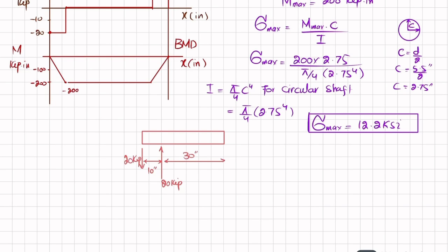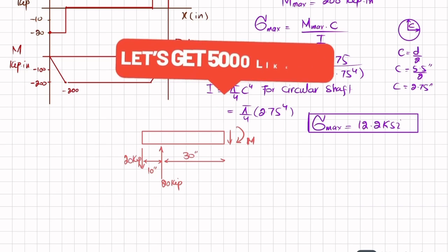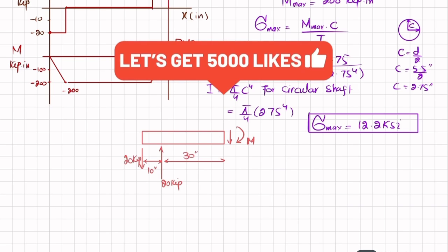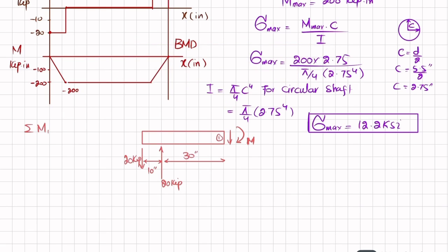So when you cut it, you will be having shear force as well as moment. We are interested to find out the maximum moment at the center. So for that, I will apply the equation of equilibrium, that sum of all moment about point 1 is equal to 0, taking the counterclockwise moment as positive.